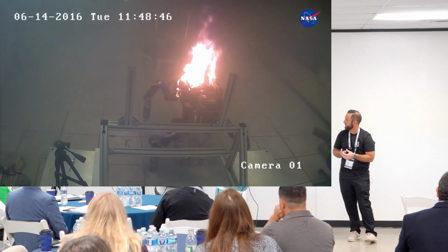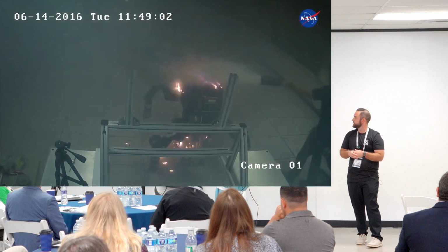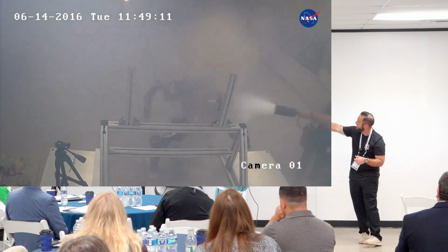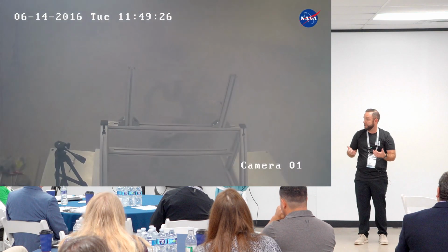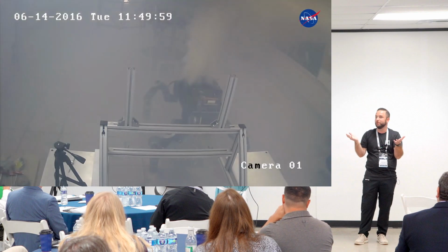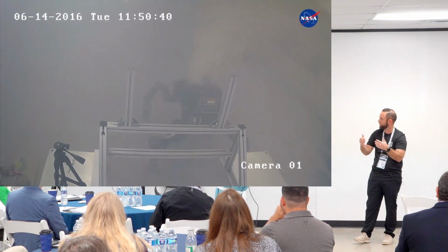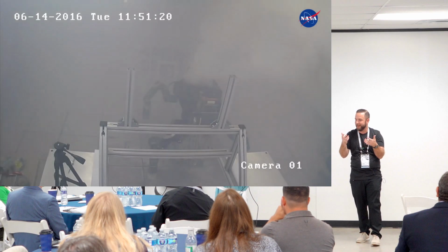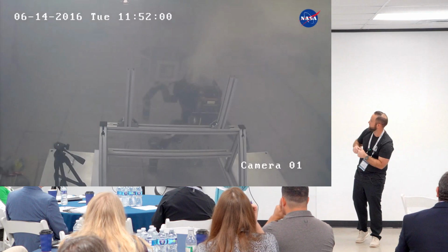What you also see happening in this event is an example that these failure modes are not just thermal, these are chemical in nature, right? If you watched the beginning of it, I believe it was an intern who came in, yeah, he's right there, he's trying to put it out with a fire extinguisher, and what does it do? It keeps reigniting, right? That's because you've got to remove the heat, because at this point, all the neighboring cells have been thermally abused. So they're entering into rapid exothermic decomposition, triggering into thermal runaway. That's why, although the extinguisher is extinguishing the event, it keeps reigniting, and that's because the cells are driving themselves into thermal runaway. It's not just the flame.